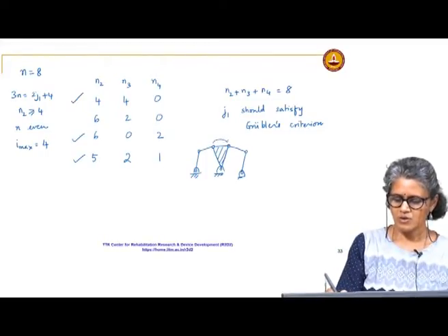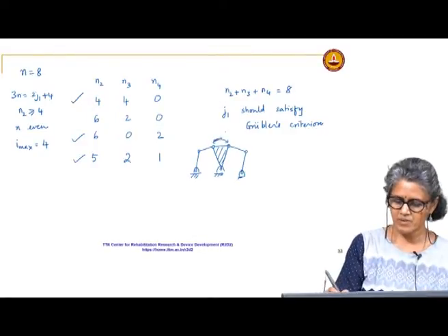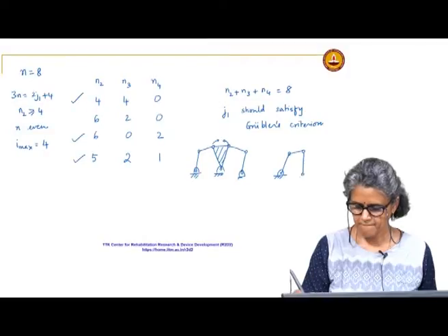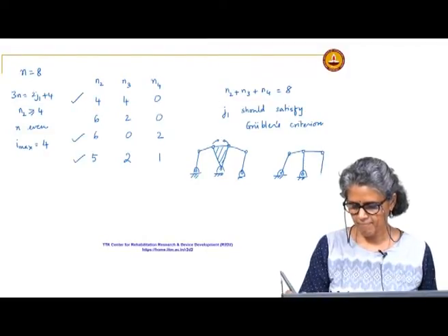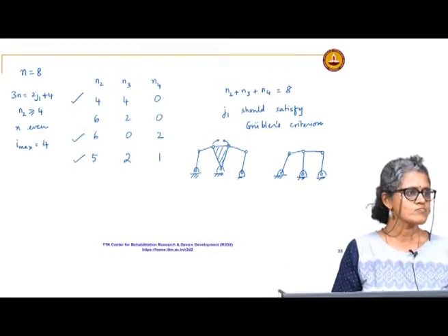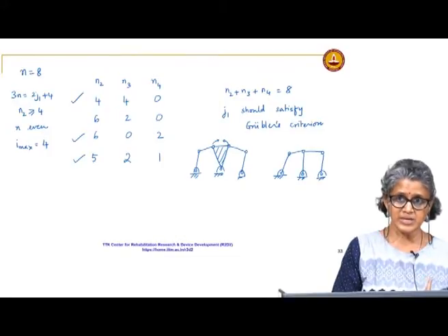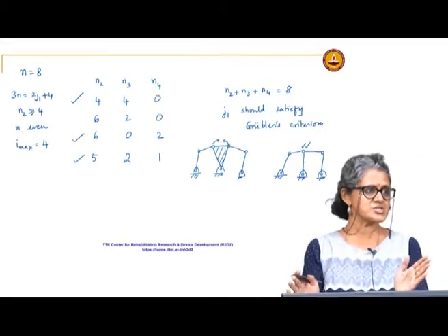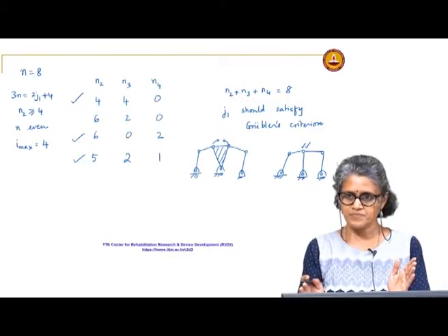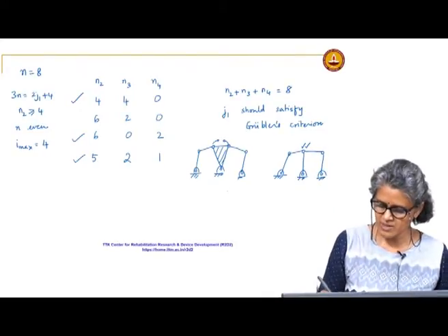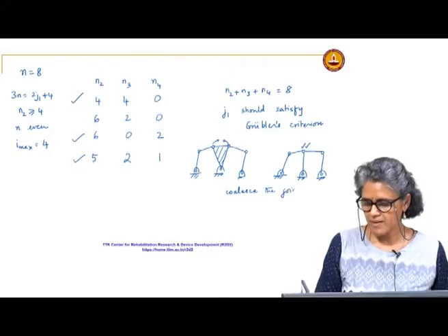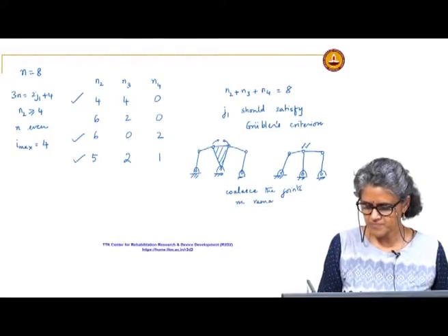I could collapse these two joints, bring them together. Same thing, only thing when I am calculating the mobility, I have to make sure that I calculate 2 J1s here. So, I collapse the joint, it did not change the mobility of the mechanism. Okay. So, basically I coalesced the joints. Okay. So, coalesce, did I get the spelling right? And M remains the same.